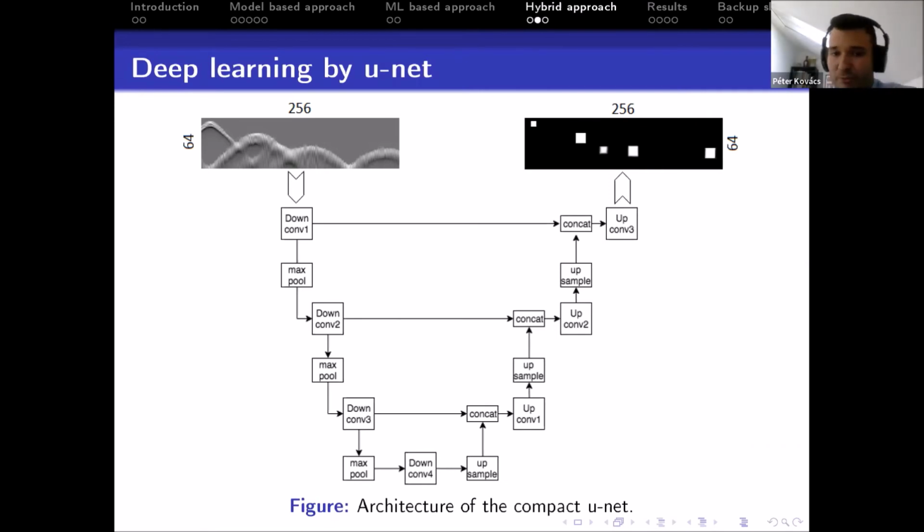The UNet has two branches, an encoding and a decoding path, where during the encoding path, the dimension of the input image is reduced, and from a bottleneck layer, the dimension of the latent space is increased to reach the dimension of the target image. In our specific case, the input to this neural network were either the surface temperature data or the virtual waves or the approximated virtual waves, and the output should be a binary image indicating the defects by non-zero image pixels.